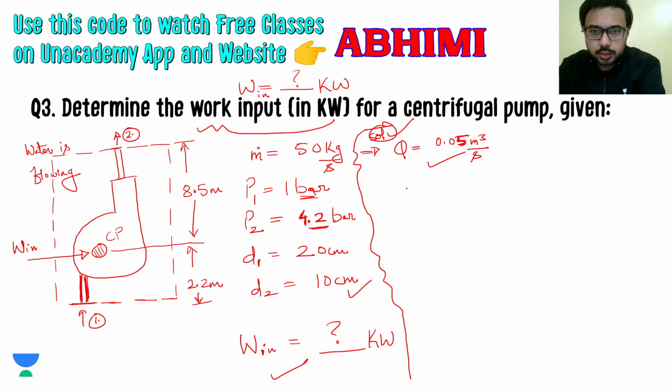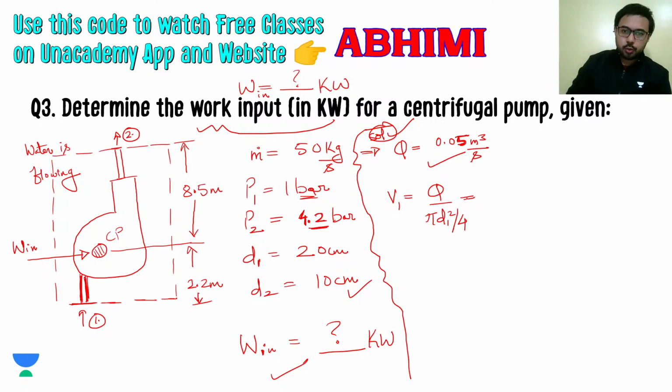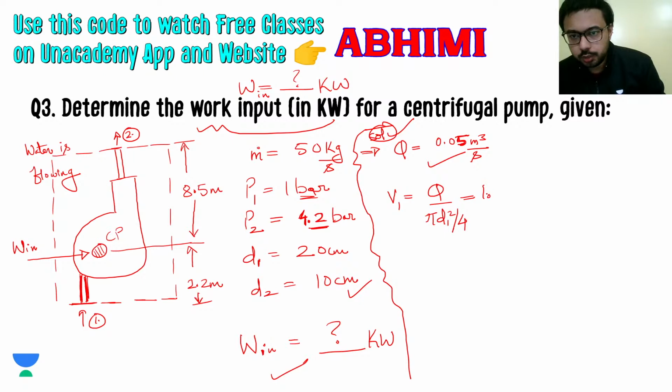And since we have calculated this Q, we can find velocity 1. That will be Q divided by pi d1 square divided by 4. So velocity 1 is coming out as 1.59 meter per second.